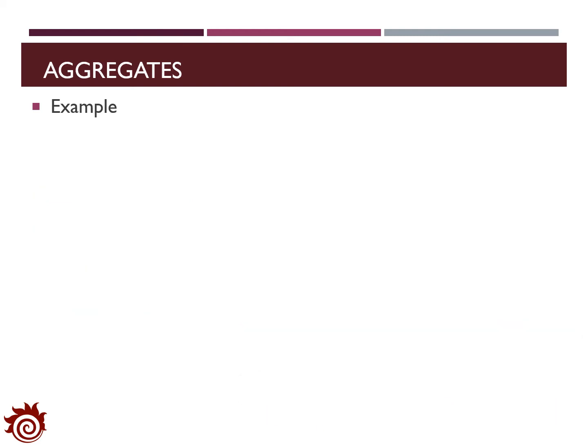Now we can summarize all the information we already achieved. First, for the filter, which is the base material we just calculated, D15 filter is 0.26 and D50 filter is 0.53.